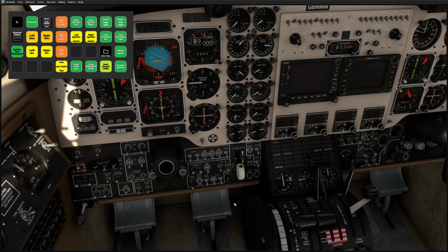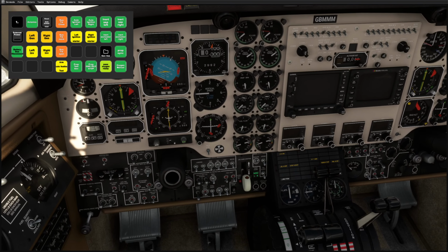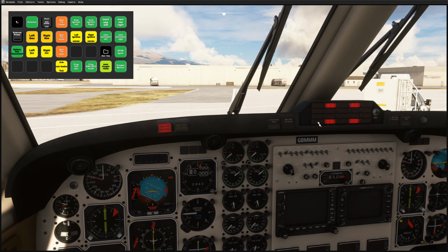We can now bring the right hand engine back to idle here. So I'm just going to tick items off on my checklist. Just checking that the annunciator has gone off. It has. You can see that the low pressure warnings will be here.